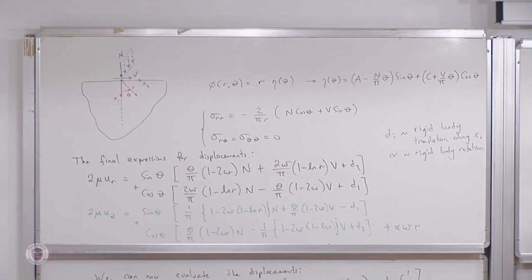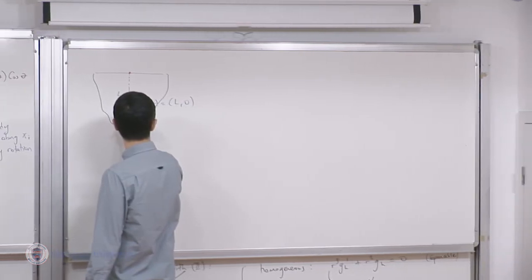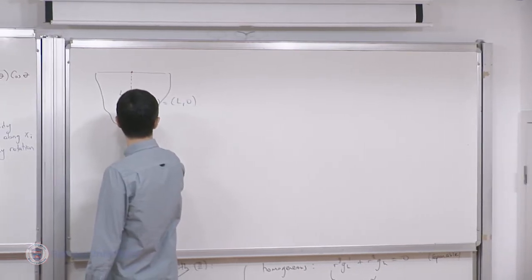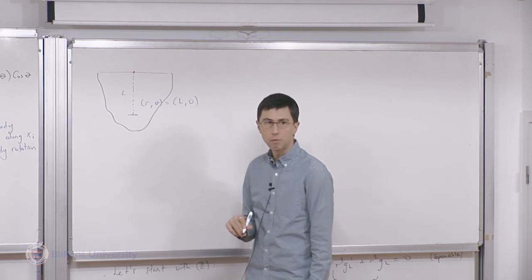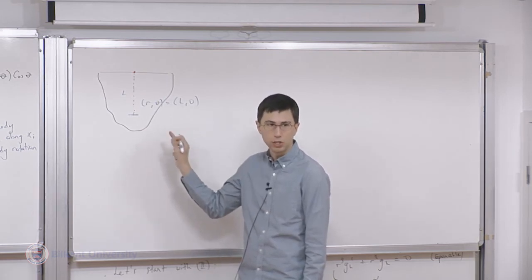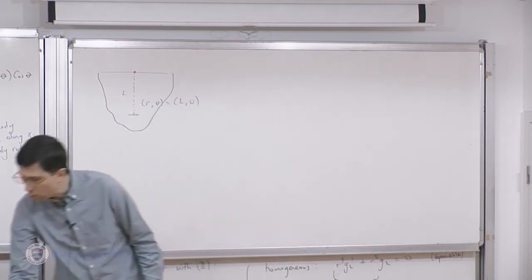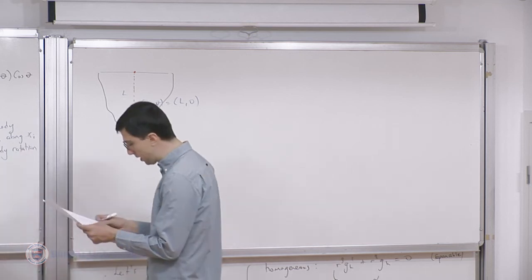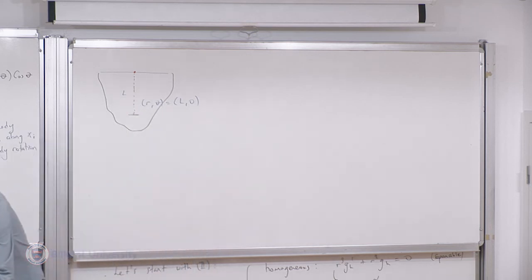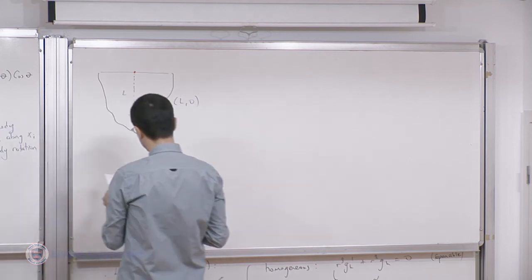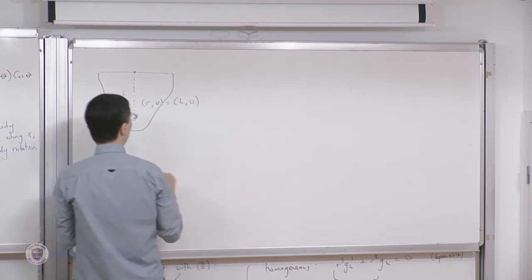That gives me conditions for which d1 and d2 need to satisfy. And additionally, and we've done something similar before when we were dealing with the cantilevered beam problem, I'm going to look at the rotation of that line, and I'm going to say that it is equal to 0. Okay? So those are the requirements that I'm going to impose. So let me just indicate what they are.